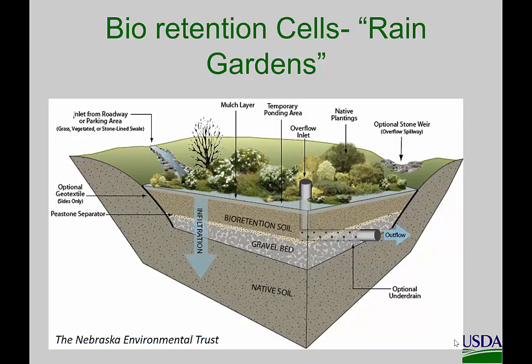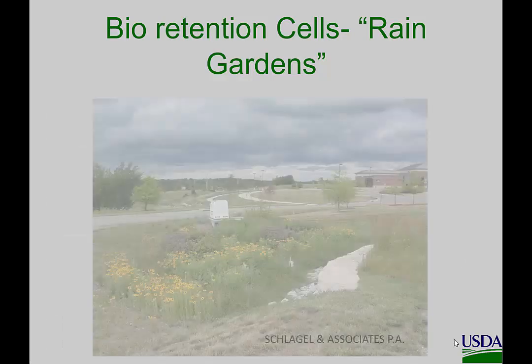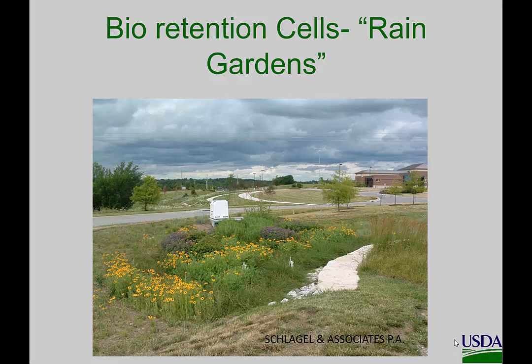That's what we have. Bioretention cells. These are popular in urban areas. Very, very similar to the blind inlets. If we replace the soil in a bioretention cell with a phosphorus sorption media, then in effect it becomes a phosphorus removal structure. Same thing. You have a media set up. Water must infiltrate through it and it filters the phosphorus before it reaches a drain. This is what they look like when they're completed. They also serve the purpose of buffering stormwater flow.